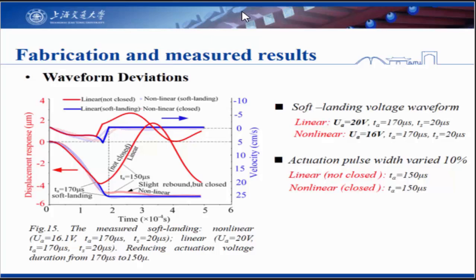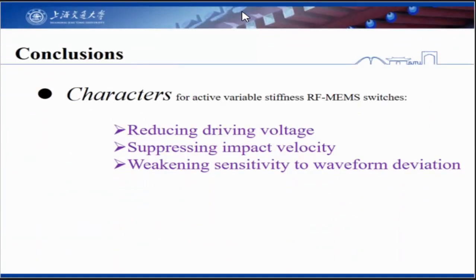So finally, a simple summary. Compared to a linear spring, a nonlinear spring can obviously reduce driving voltage, suppress impact velocity, and weaken sensitivity to waveform deviation, which can enable extending the lifetime of RF MEMS switches.